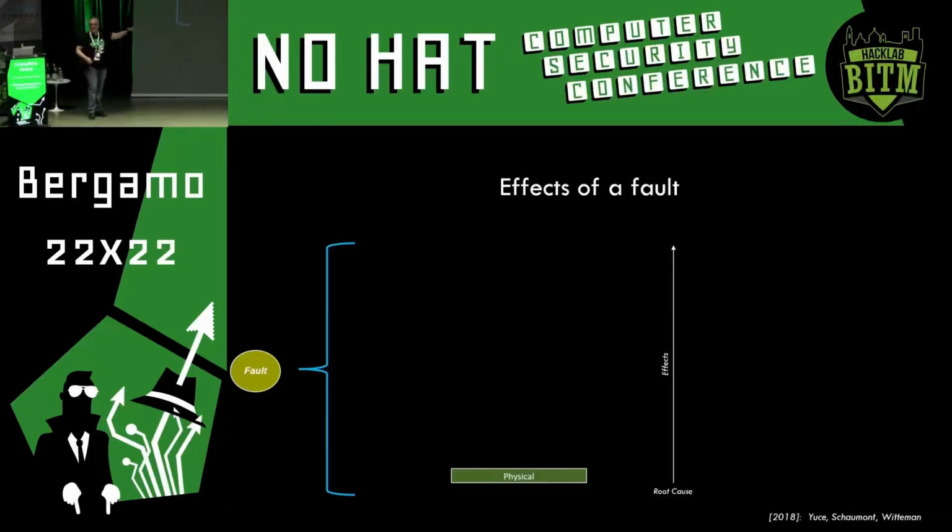It's physics. Let's say, we're not going into the details of VCC, clock and laser, but maybe, for example, the values at gate output are not sampled correctly because they are not ready, for clock glitching, or because there is not enough energy for representing them, voltage glitching. So this is actually happening somewhere in the chip at the physics level. Of course, on top, there is just the circuit. There is not only the gate, there is a net. You know, the netlist that you might have heard, all these things, it's a net. So the misbehavior of one single gate is going to affect the logic on the rest.